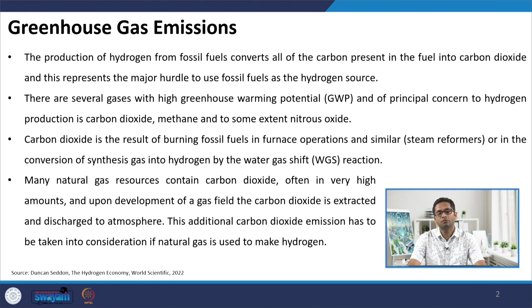Then another major source of carbon comes after the water gas shift reaction, where after all the carbon monoxide has been converted into carbon dioxide, I would want to remove all the CO2 so that I can get a pure stream of hydrogen. There could be different technologies which could be utilized for the removal of this CO2, but herein also I get a pure stream of CO2.